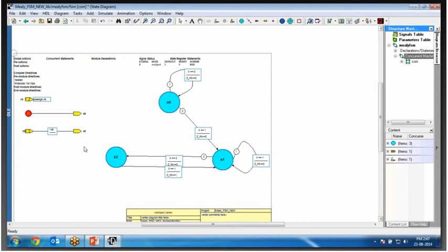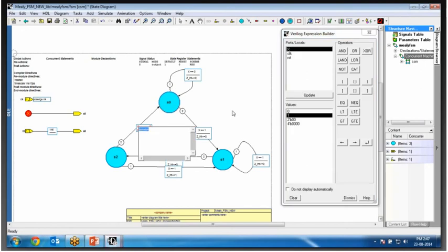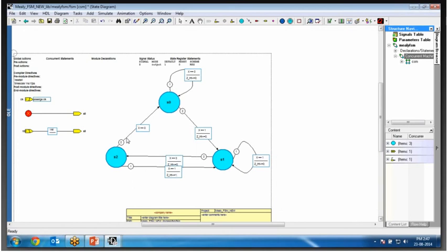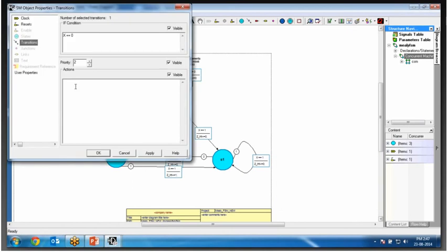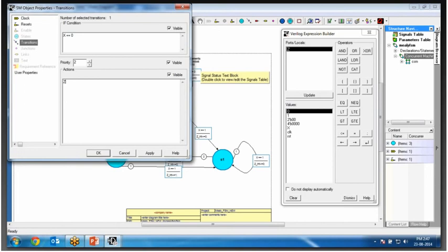What happens after finding 1-0? If we get another 0, we have to start all over to find the pattern. So the final transition is, after getting 1 and 0, if we again get 0, go back to the default state. So if x equals 0, go back to state 0. That is the default state. Again we assign an output, because z_int cannot be 1 for a pattern that has not been formed. So assign z_int a value of 0 because the pattern has not formed. Click on apply.